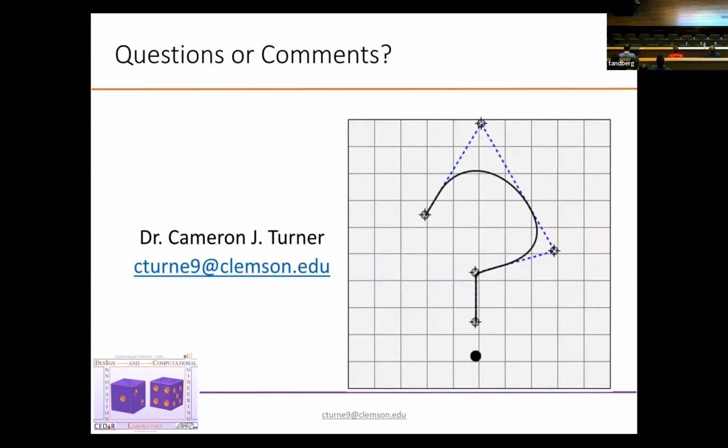Any questions? On the disk problem, how does one go about validating those models? What measurements do you take to calibrate it? So what we started with is we would start basically with one disc between two vertebrae, and we would use the kinematics of the back to provide different loads that were typical of what are experienced by vertebrae that are kind of known on the disc, and look at how the disc deforms under those loads and whether or not it provides acceptable deformation so as not to impinge upon the spinal cord.